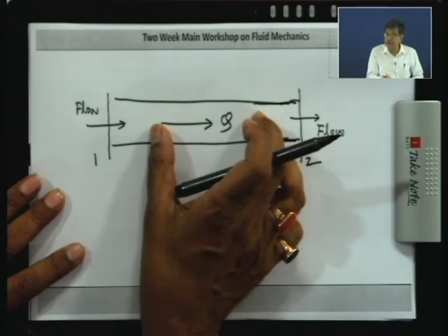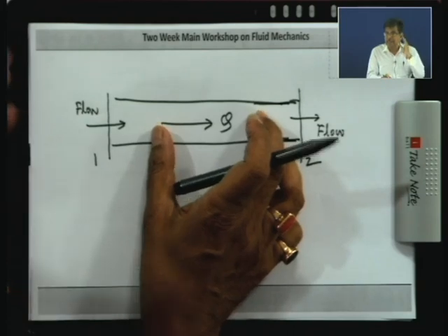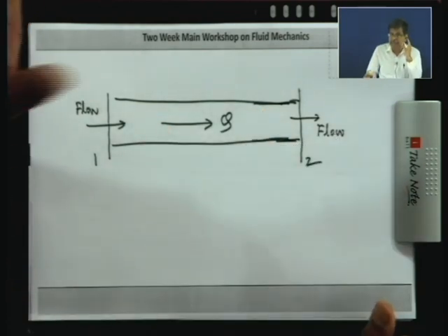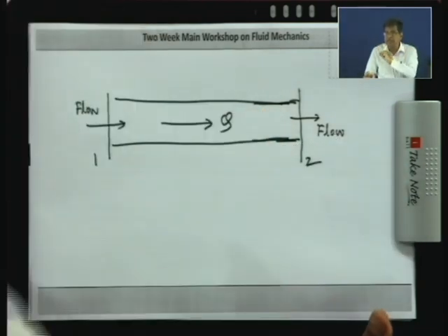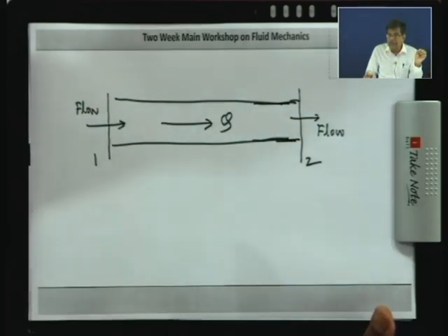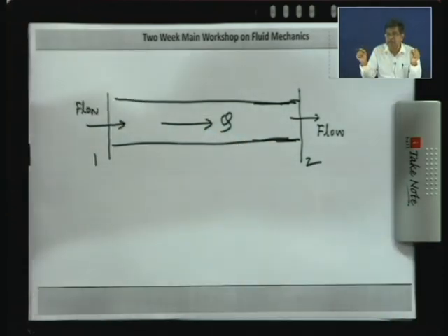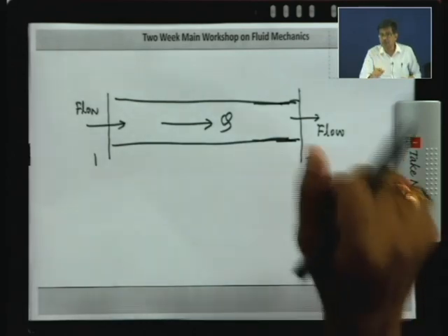And this is the Bernoulli's equation that tells that total mechanical energy at inlet, if you take along a streamline, then at any point at the upstream and any point at the downstream, the difference of energy equals the total energy loss along the flow. What is this loss? That has to be emphasized. I think Professor Suman Chakraborty has already emphasized this. Energy is neither lost nor created.